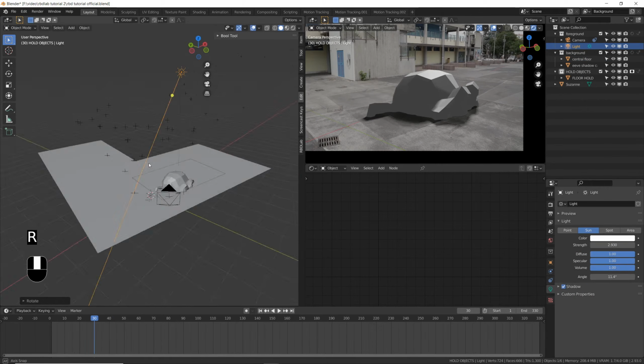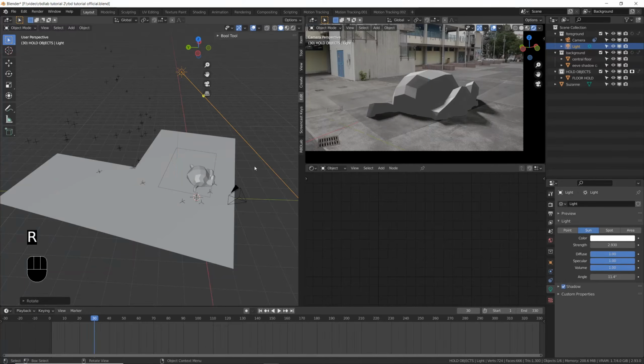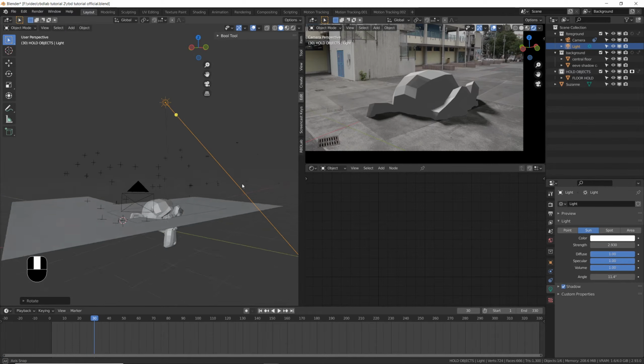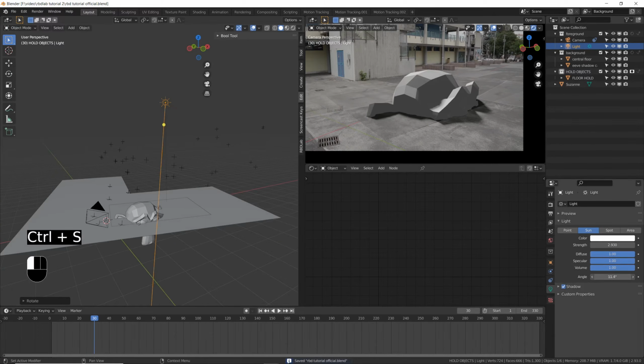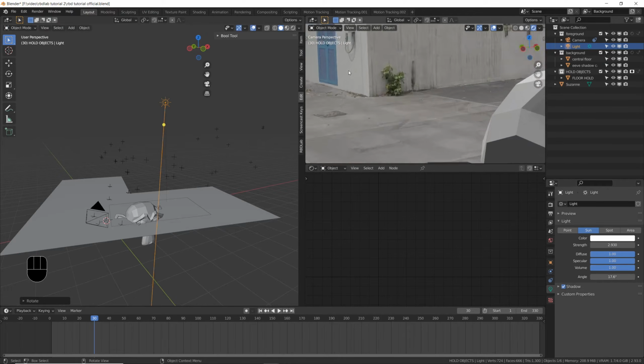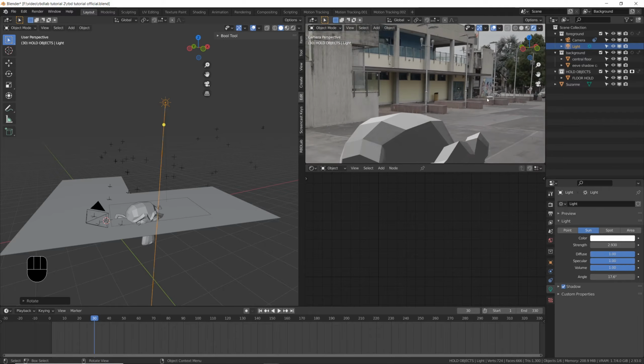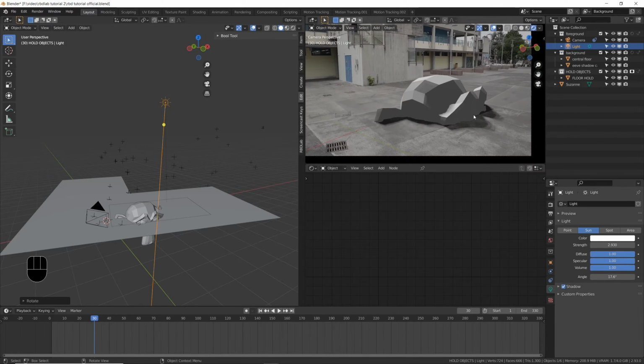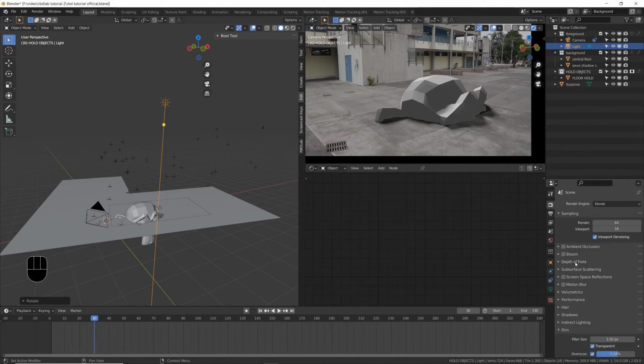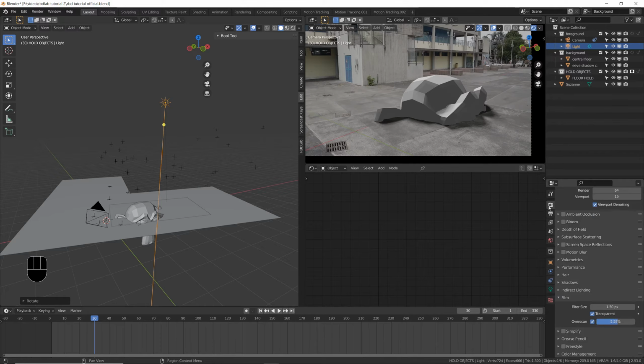just to have more shadows, something like that. We can even increase the angle to have more blurred shadow, because I see that even in the original movie the shadows are very blurred, also almost invisible. So I'm gonna do this in my light, maybe put in something like 24, and let's make sure that you increase the quality of the shadow in EV settings here. Shadows 4000, high bit depth if you want.